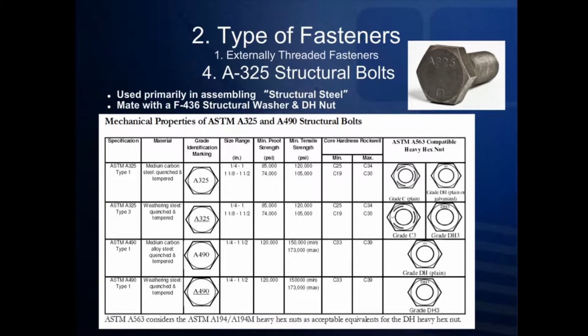Structural bolts are specifically designed for use with heavy hex nuts in the connection of structural members as opposed to tapped out holes. The nuts for structural bolts shall conform to the ASTM A563 spec. The following chart exists to assist in proper structural nut selection. As you can see, grade C and or grade DH heavy hex nuts are the proper nut that you'll want to mate with the A325 structural bolt. However, one should realize that ASTM A563 also allows grade 2H nuts to be mated with A325 structural bolts.